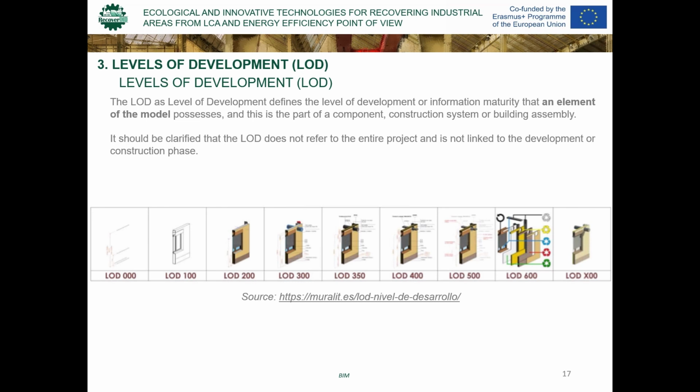However, as we will see below, the British have their own standards, defined as levels of detail, rather than levels of development, which, being more focused on graphical aspects, range from LOD 1 to 7 and are called LOD 1 brief, LOD 2 concept, LOD 3 design development, LOD 4 production, LOD 5 installation, describes the construction, LOD 6 is built, and LOD 7 asset information model, asset information.